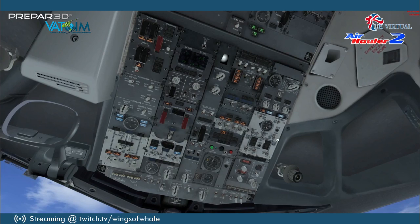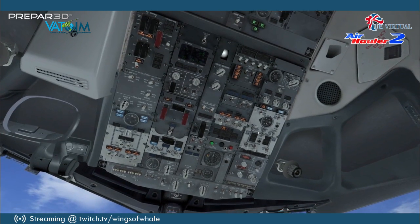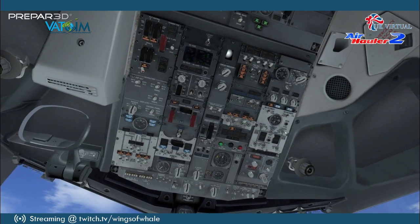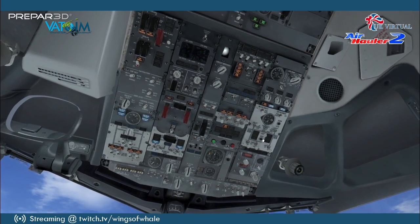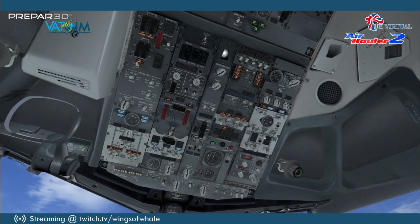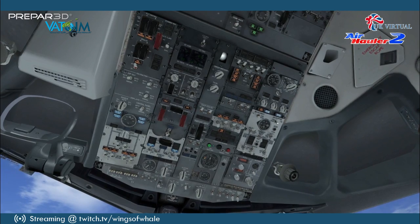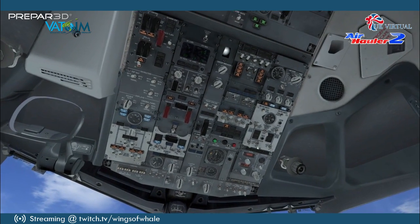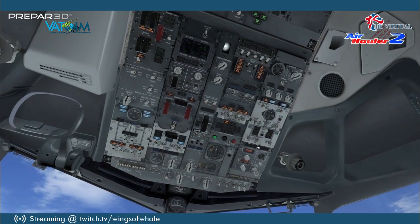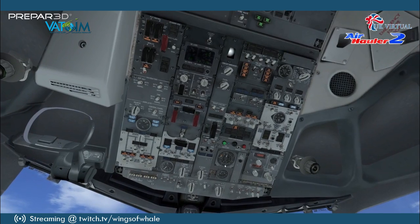So those two engine pack switches need to be either off or they can be in the auto position, but I prefer them to be off myself, so I know they're off. Isolation valve stays open, recircs stay on auto as they are, and then down at the bottom your APU bleed needs to be on. So we're in position now, ready to start.